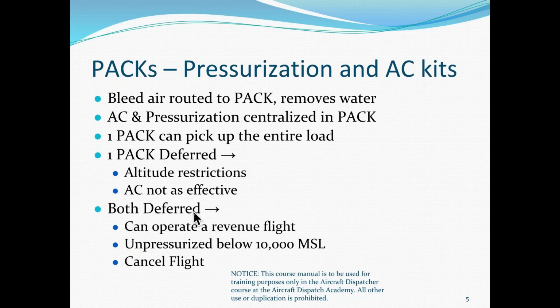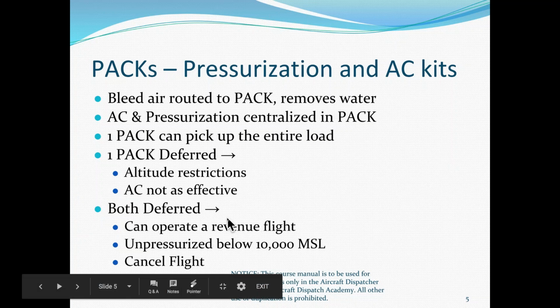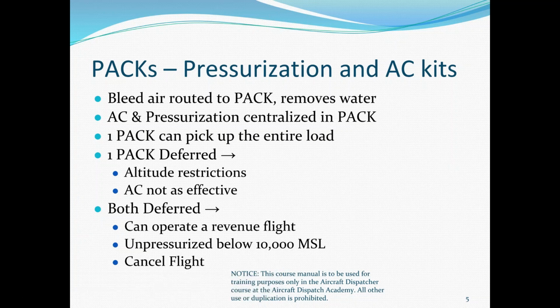But if they're both deferred, basically they won't let us operate, but technically you can. You just have to fly unpressurized below 10,000 feet, and most of the time we just cancel the flight because of that. If you were to continue to operate the flight, you'd want to be in a cooler environment, and it would have to be extremely short hops.